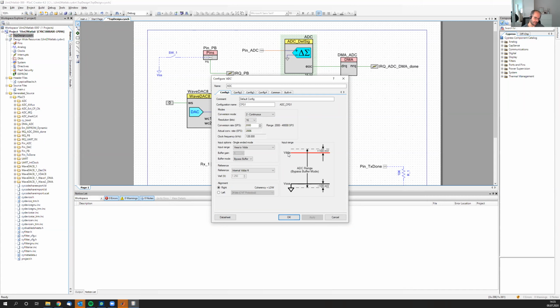Now, we could try to bypass on a pin. So the idea here would be you bring in an external reference voltage, or you use an internal reference voltage, to say I know that this reference voltage which is coming in has a fixed voltage, and you can take that as a reference. That's why it's called reference here, to calculate the absolute voltage, right? Is this clear to everybody? Like where I want to go with all that?